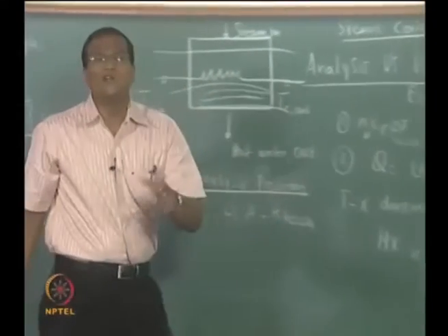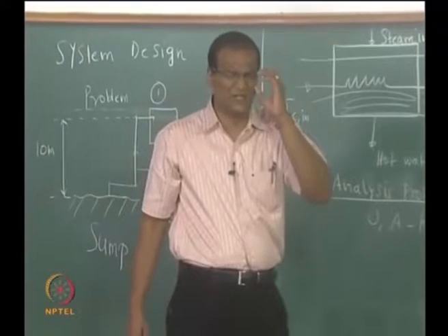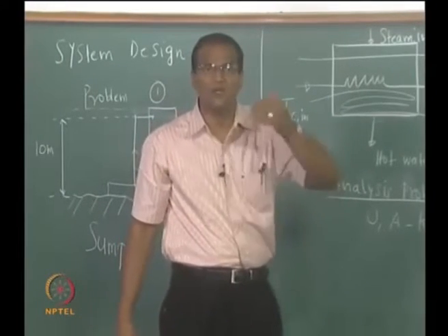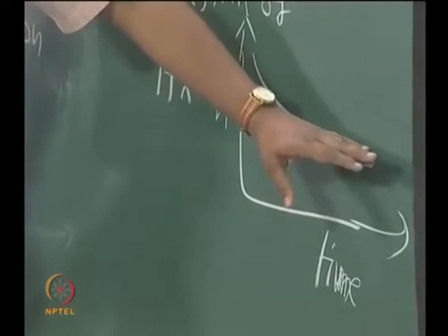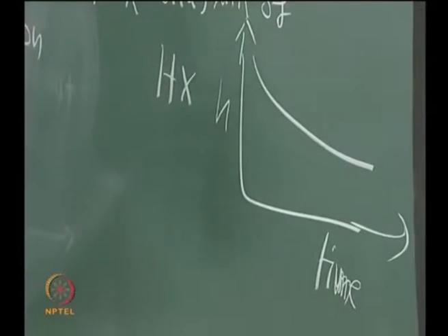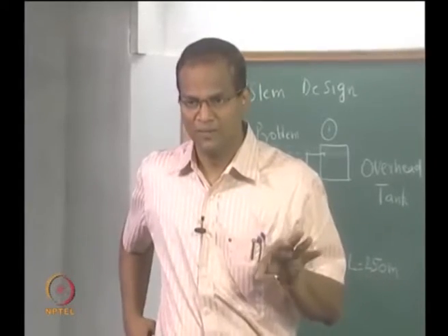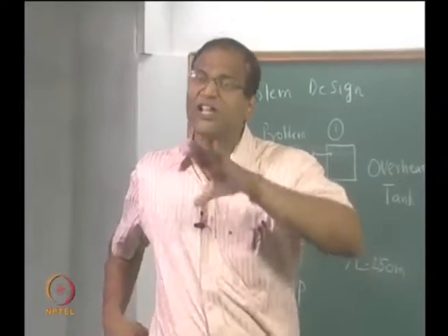So design of heat exchangers or design of heat transfer equipment for life is not such a straightforward task. Suppose you want to design it for 15 years, you have to consider all this. There may be something like what is known as an asymptotic fouling factor. Eventually it will settle down to a fouling factor that can be obtained by doing calculations and so on. Are you getting this point? So design will involve all this.